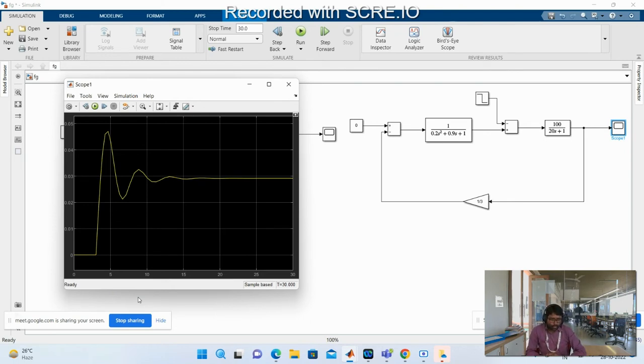Hope you understand these are 4 block diagrams. Now the question is, if you observe free governing operation, or first order free governing operation, there is some frequency deviation. Frequency deviation 0 means your system is operating at the nominal frequency, that is 50 Hz. But if there is a frequency deviation, that means your system is not operating at the nominal frequency, 50 Hz. Actually, our motto is to operate the system at the nominal frequency. Slight variation is okay, but you have to maintain near your normal frequency, that is 50 Hz.